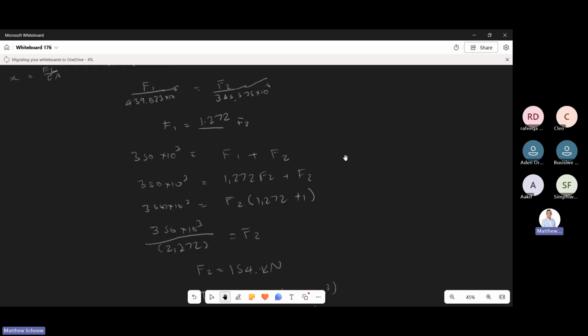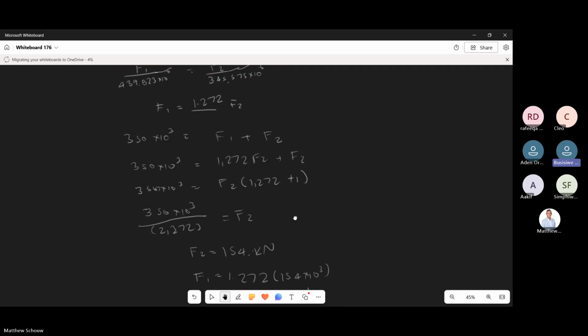That's fine. Then I say 154 divided by pi over 4. Hope you guys got the right diameters. Okay, and then bracket 0.08 squared minus 0.06 squared. And how much did you guys get for the stress? Stress for steel is 89,122.